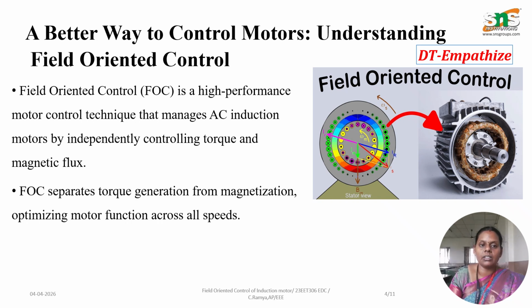Field-oriented control is a high-performance technique used for controlling AC induction motors. It works by independently controlling the torque and flux magnitude. By separating the torque production from the magnetization, FOC ensures efficient motor operation across all speed ranges.